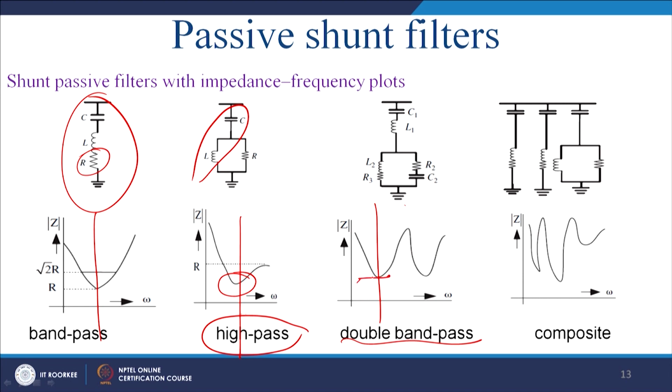So, it is a minimum impedance and this is a minimum impedance, and when you get a minimum impedance, it will be a sink for the fifth harmonic or seventh harmonic. So, you can eliminate both, and you can have a composite. You have this and this, thereafter this, then you can eliminate any other frequencies like this. This will be a zigzag line.